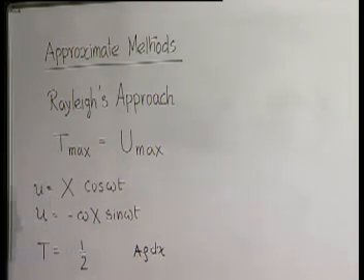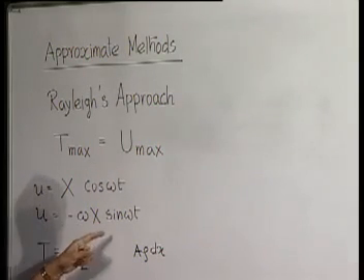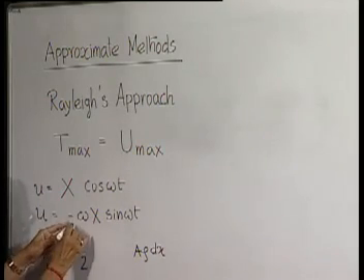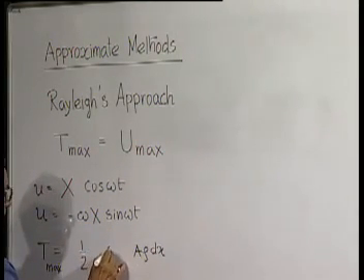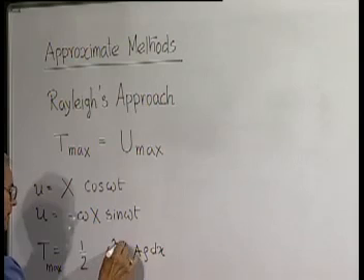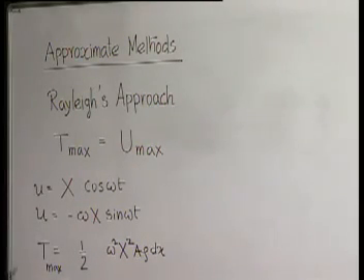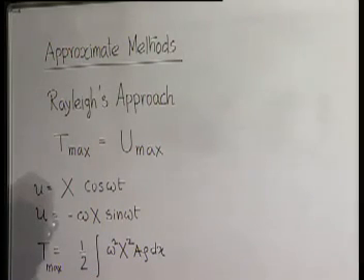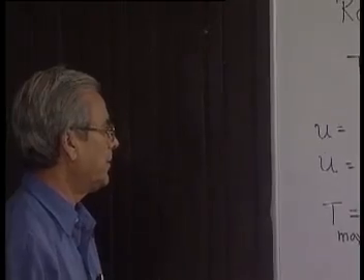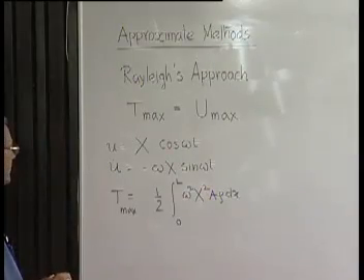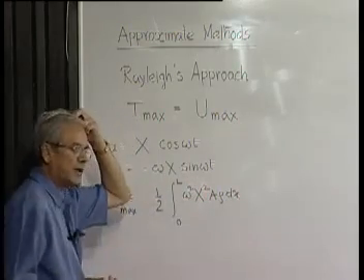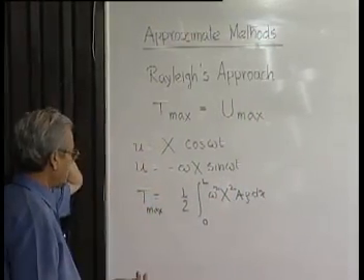and maximum velocity will be omega x, and so therefore square of that. This has to be summed up for all the elements. That means we integrate for the whole bar or beam or shaft, whatever it may be. Of course, since it is linear deformation we are taking, we should take either beam or bars.